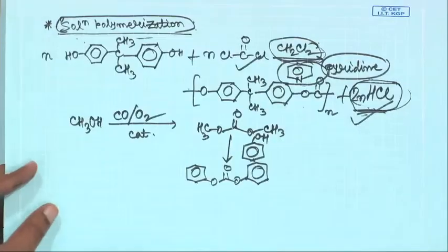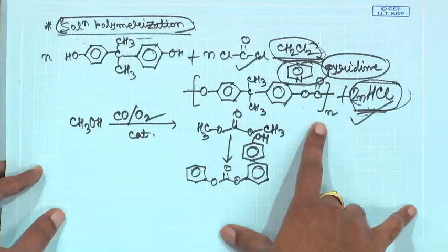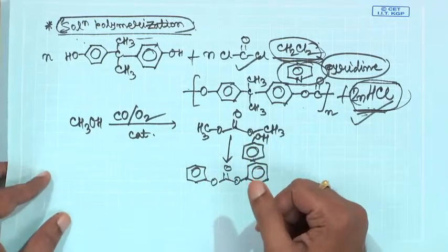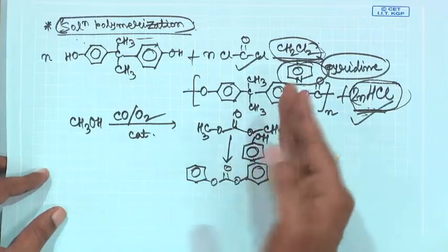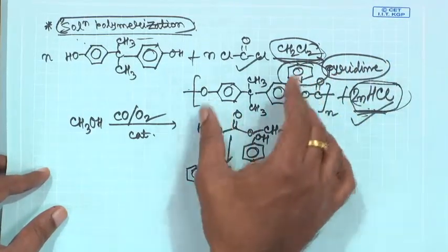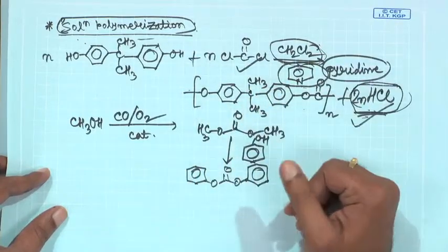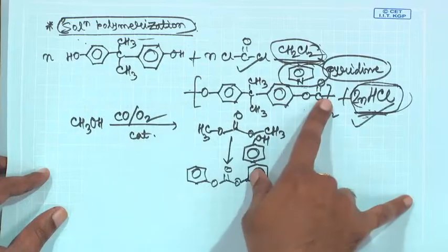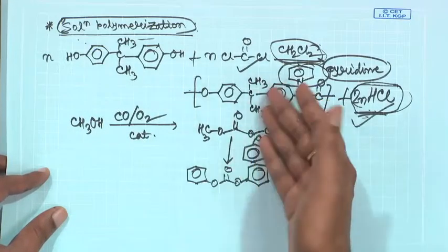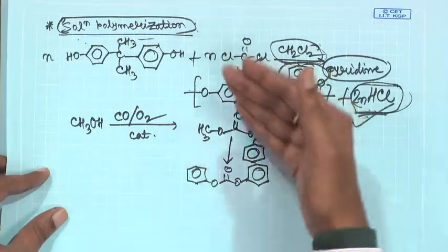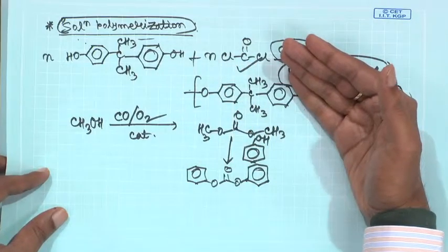So, above that temperature you start to lose properties like your mechanical strength and stiffness. Typically, if the glass transition temperature is higher for a material, then your properties can be maintained up to that much higher temperature, which is an advantage. So, if you have an aromatic ring, because of the rigidity of the system, your properties can be maintained up to a higher temperature, because the glass transition temperature becomes higher.